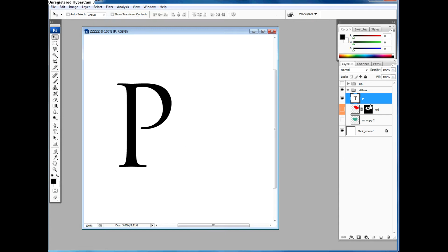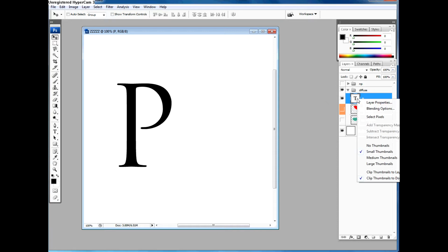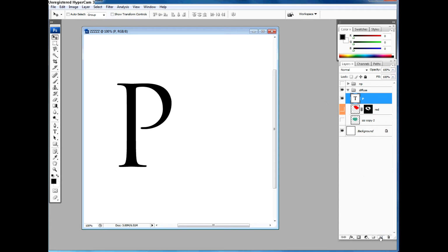What I would do is, when you do a text, sorry, I'm going off the topic a little bit, I won't be able to edit it until I flatten it. There's a few ways to do it, but what I usually do is create another layer, which is this one. Select it, hold Control, select the text. So select the layer, select the text, and I do Control and E. Now it's a flattened layer that I can edit.